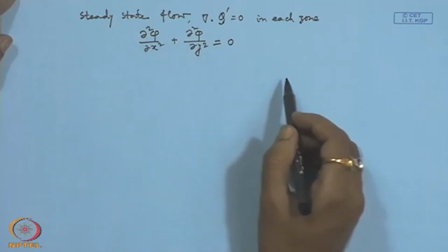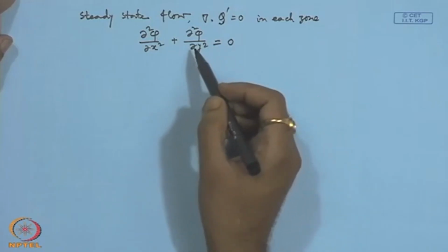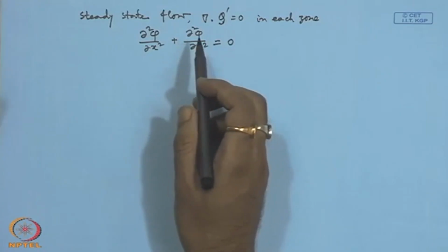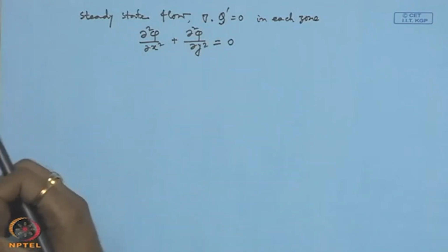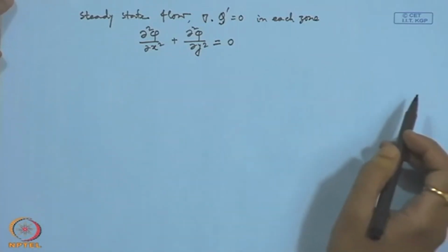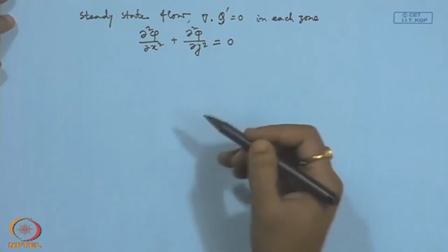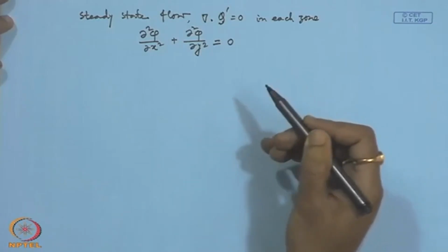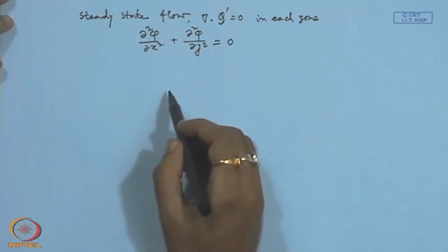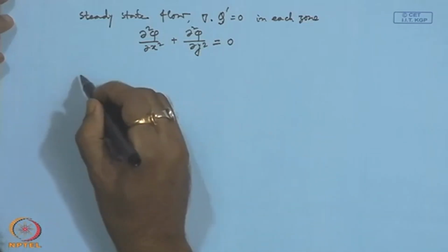So, this means that phi is a harmonic function in the respective zones, so it satisfies our Laplace equation. Strack utilized this particular approximation and theory for derivation of coastal aquifer modeling with a single pumping well, and he showed that phi can be constructed as